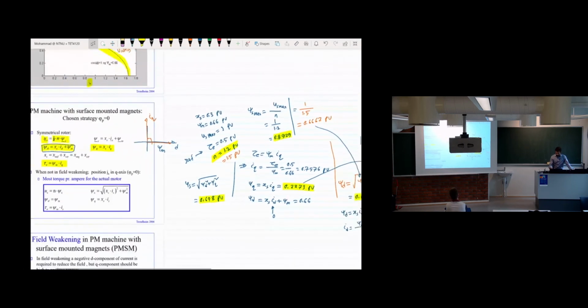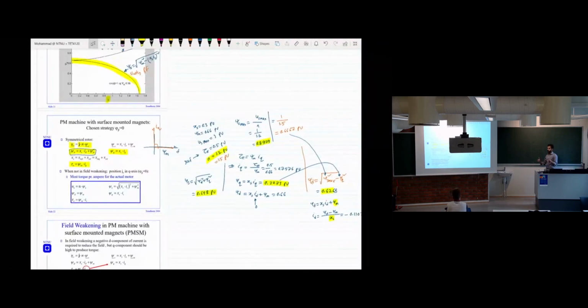The calculation I have done here, we can put in the software. When we program the control, we put the calculation inside the software so that it calculates automatically how much d-axis current we can provide. So the main target is the d-axis current.